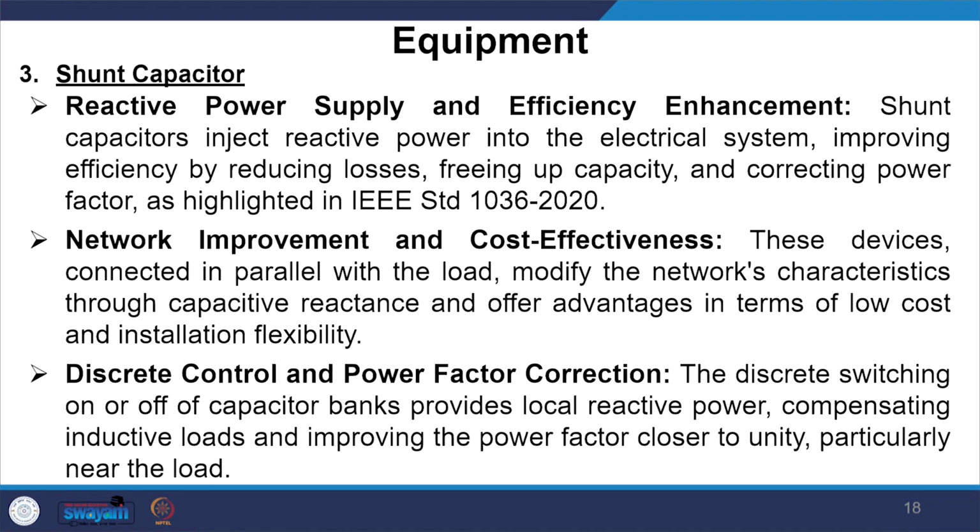capacity and correcting power factor, as highlighted in IEEE 1036-2020. Now, these devices connected in parallel with the load modify the network characteristic through capacitive reactance and offer advantages in terms of low cost and installation flexibility. So, this is one of the cheaper devices, a cheaper solution I can say, which can be achieved